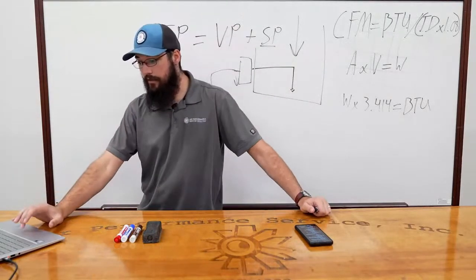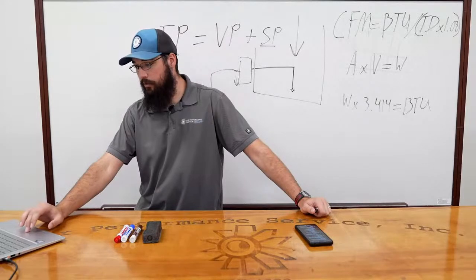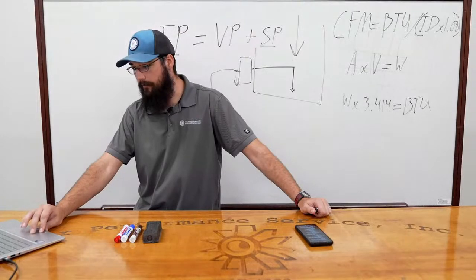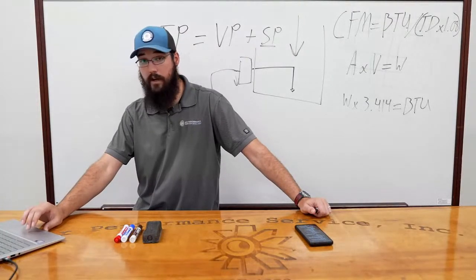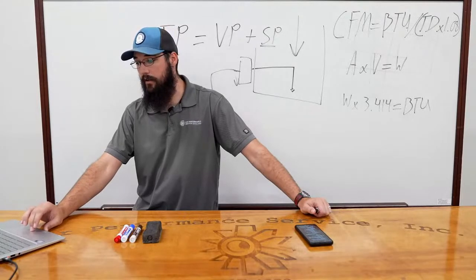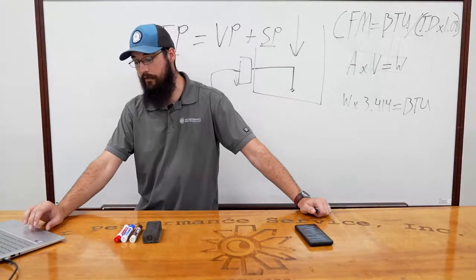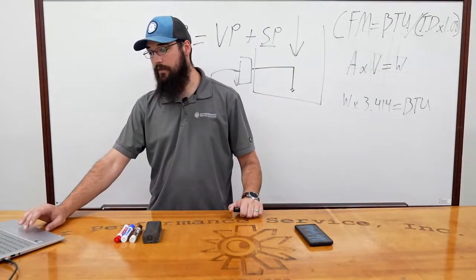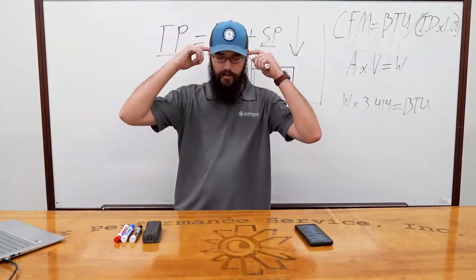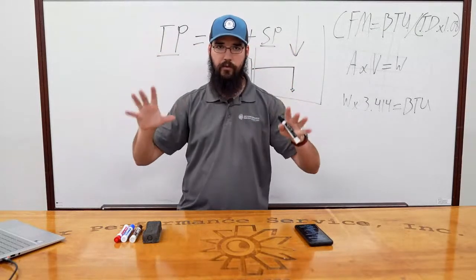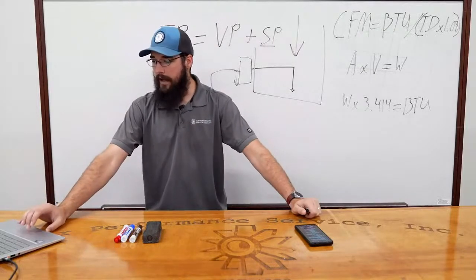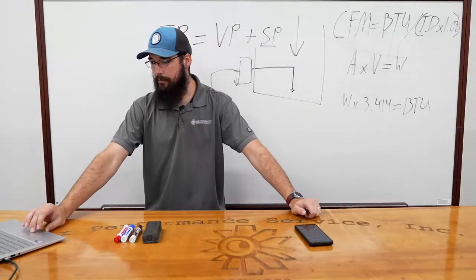You can do a lot of things with it. What I want to represent is, in most cases, our smaller pulley is our drive, our motor pulley, and our fan drive pulley is going to be the larger one typically. If I try to sort this out in my head, I will quickly confuse myself as to what's actually happening. So I would recommend having a tool like this because it can really help you determine.